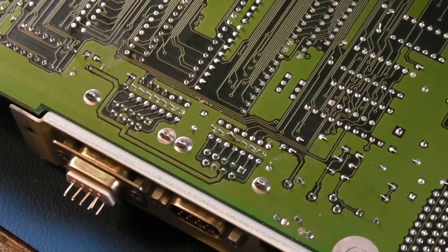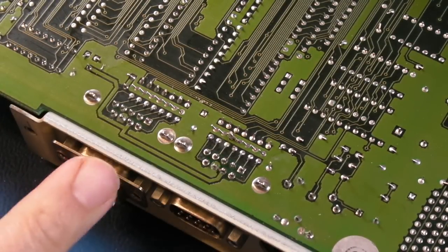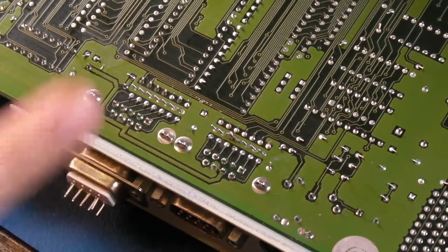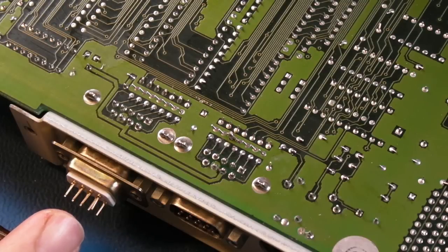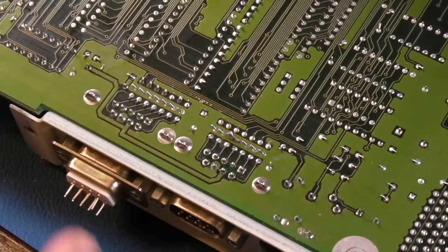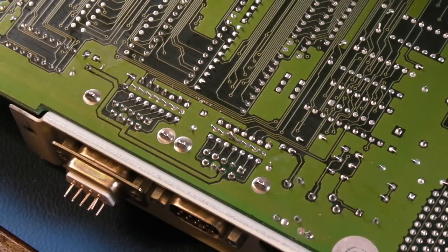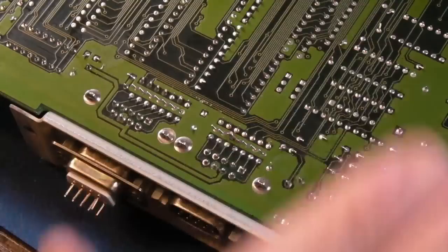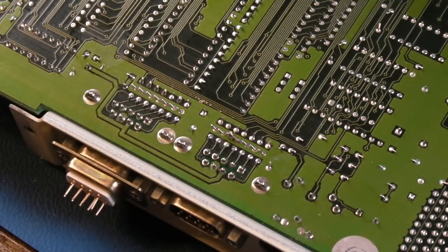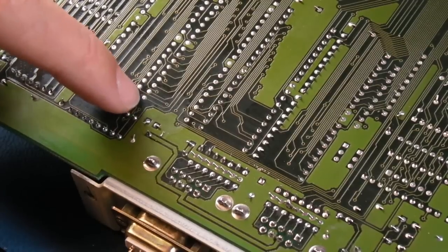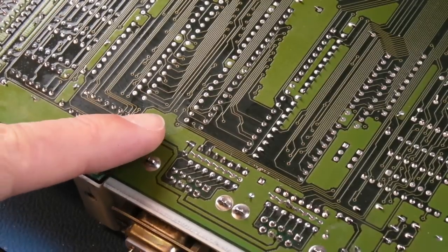Right now though, I'm having a hard time trying to make connectivity between either of the ports here and the Paula. Now I thought the pot X and pot Y, two connections on each of these, should go straight to Paula, and I'm not seeing anything anywhere, not a single connection. But the weird thing with that is the analog works on the mouse. Both buttons work on the right port, only the left button works on the first port. So I don't know. Anyway, I'll clean this up and just inspect around there. There is a wee bit of corrosion here as well, and you can see it just like fuzzy.